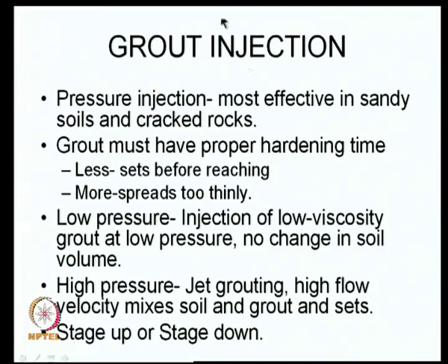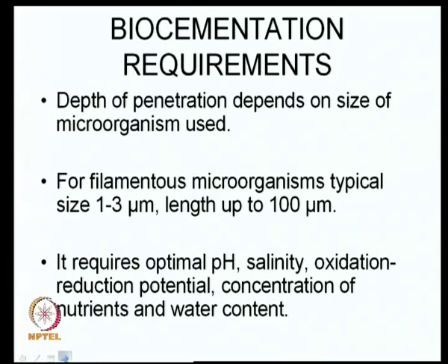And we know about the method of grouting: pressure injection grouting can be done in sandy soils and rocks. We also studied that the grout must have proper hardening time, and low pressure is required in the case of low viscosity grout, with no change in soil volume. For high pressure there is another classification we already studied, jet grouting, with high flow velocity mixers, and there are a lot of issues that we already studied.